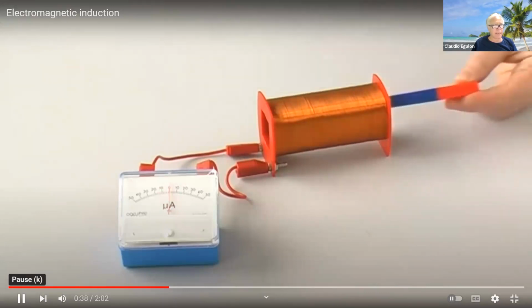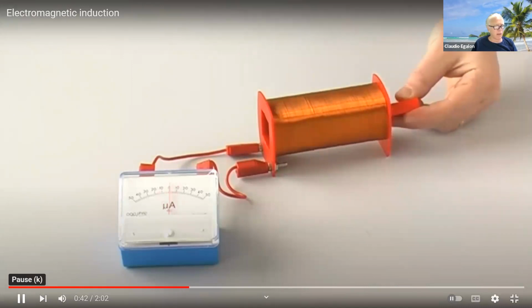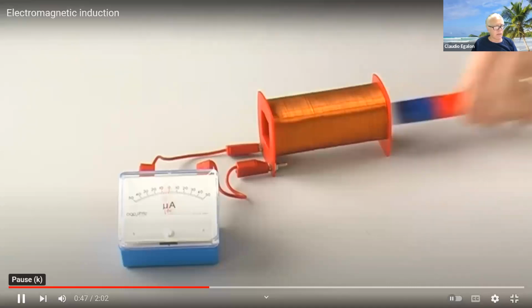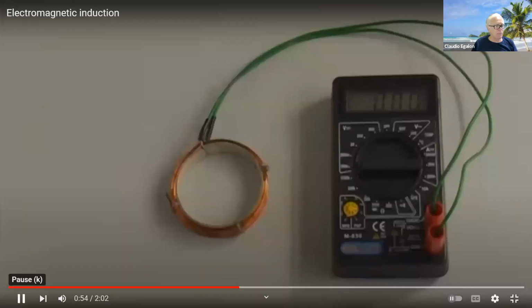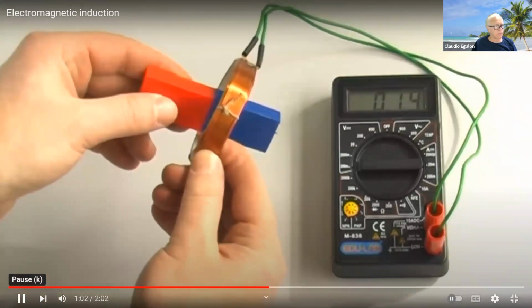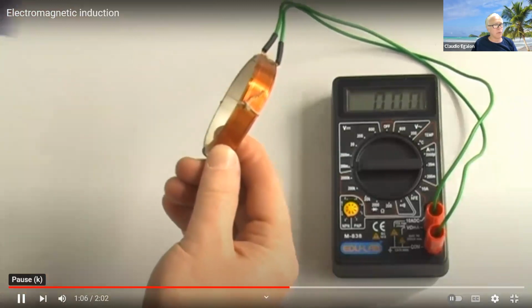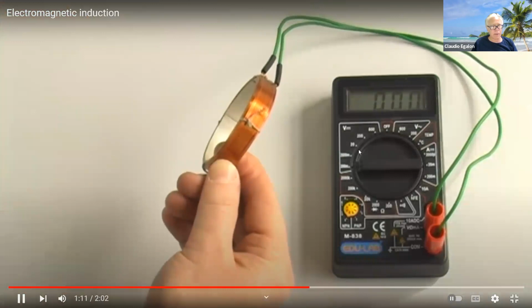You can do that with a magnetic bar, but you can also do it with a current flowing through another circuit. You can get a second circuit that carries a current. That current generates a magnetic field, and that magnetic field can be used to induce a current in a second circuit. So here's another loop. There is no battery in this loop. Here you go, the other ammeter. It's a very cheap ammeter, this one here.